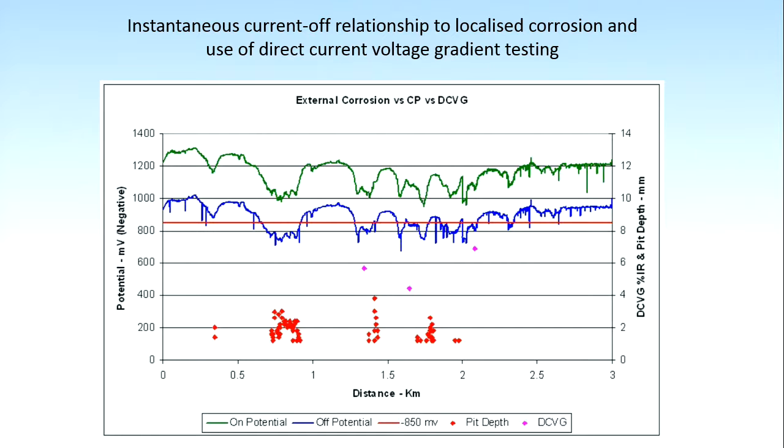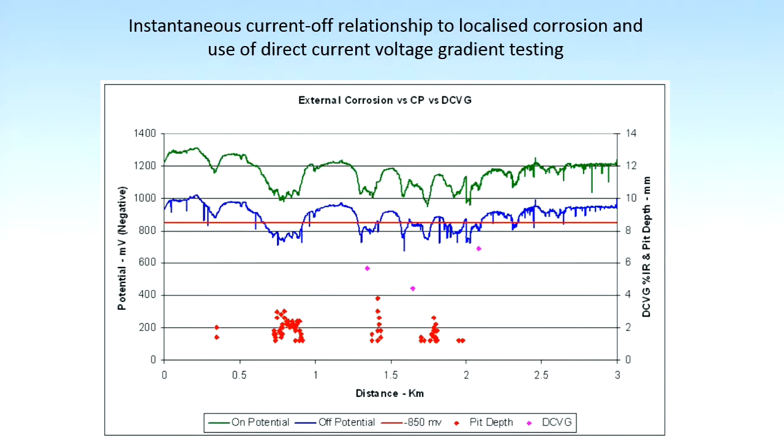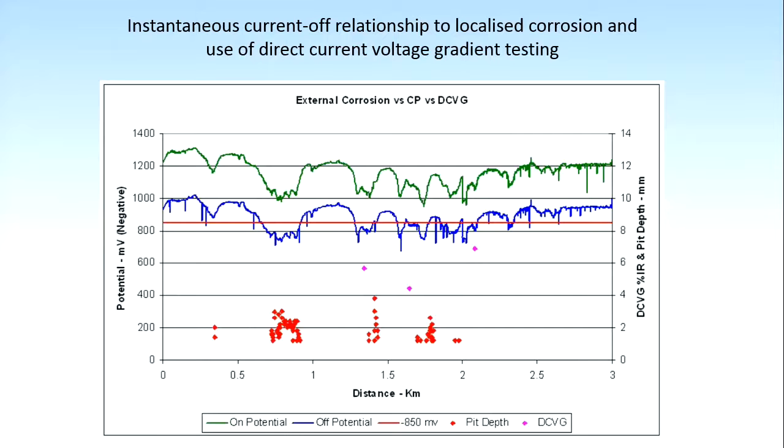These abbreviations here, essentially we've got three types of coating. We've got plastics, so 3LPE stands for 3-layer polyethylene, and 3LPP is 3 layers of polypropylene. So we've got plastics, and then the next one up, where's the mouse gone? There it is, are the epoxies. So FBE stands for fusion bonded epoxy, and then liquid epoxy. So epoxy resins, which